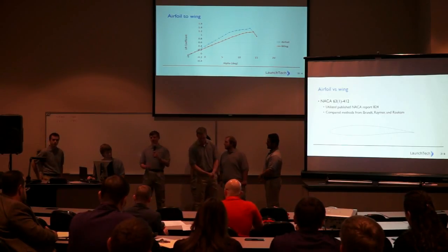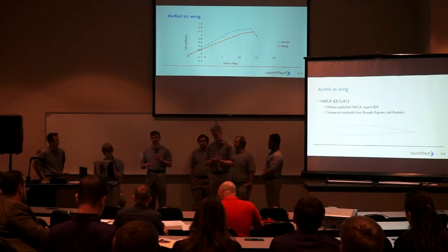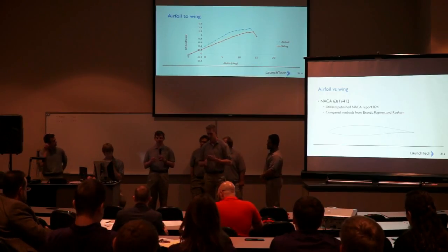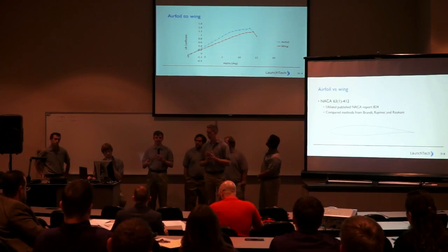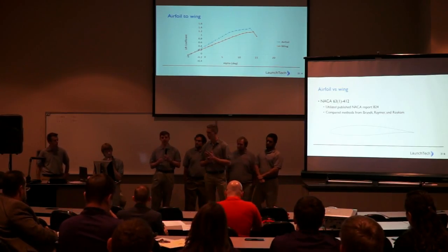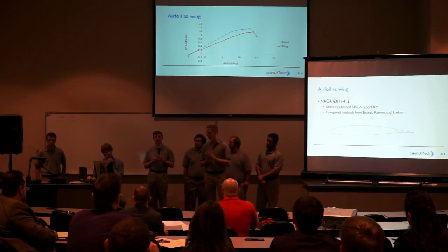The airfoil itself is just the regular airfoil plane. However, the wing analysis, the wing plot in the orange, doesn't take into account the extra aspect ratio from the winglet. Does or does not? It does.